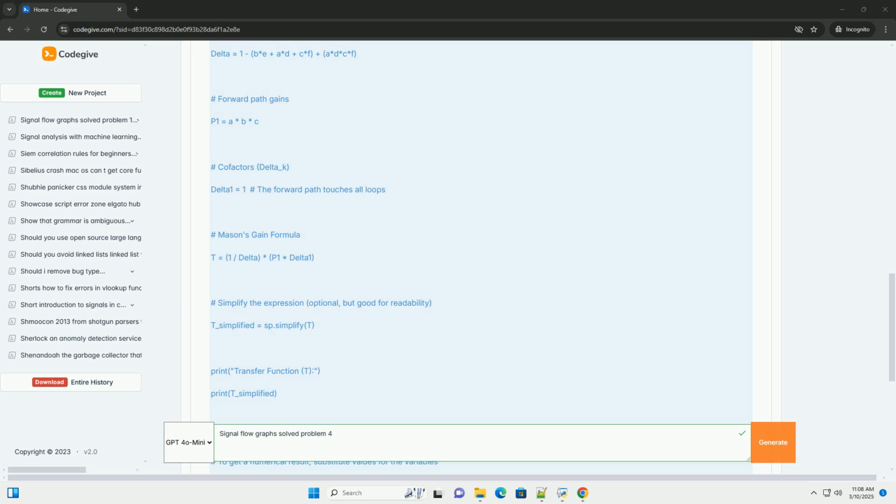Key takeaways and general approach. Draw the SFG. If you're given a set of equations or a block diagram, the first step is to accurately draw the signal flow graph. Make sure to label all nodes and branch transmittances. Systematically identify paths and loops. Carefully identify all forward paths, individual loops, and non-touching loops. This is the most error-prone part of the process, so double-check your work.